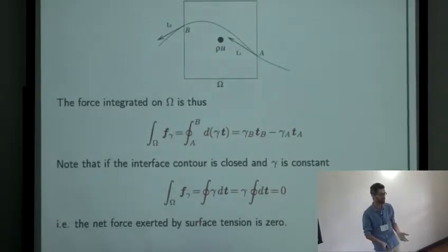Of course, it's worse because usually it's resolution dependent. So if you are trying to simulate multiple bubbles and droplets everywhere, and you're interested in average properties, of course average momentum transfer, you're going to use a very coarse mesh, and usually this effect is going to be much worse, okay? So it's actually important even when you derive average quantities. You could say, oh, it doesn't matter, maybe they are uncorrelated, they are random forcing, right? It's a sort of Brownian motion. But unfortunately, as usual, Murphy's law: they are actually correlated, so your thing is actually moving around in a definite direction. So that's pretty bad.